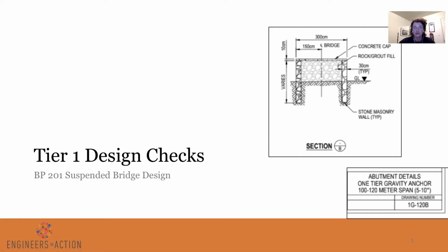Tier 1 assumes you are using standard drawings, and the design process is very linear. By this, I mean you set up your inputs based on bridge geometry and materials available, calculate a series of outputs from standard equations, and choose the closest standard design that works. As described in the previous section, this is not a bad thing, but in order to increase efficiency, further customization will be required, and therefore delving into the assumptions behind the prescribed equations will be required in Tier 2 and Tier 3 analyses.